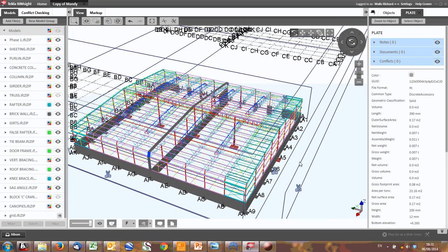When the wind blows on this side of the building, how do those loads get supported? If you don't know where the loads are going, you have a very big problem. That may mean your structure is not stable. You need to be able to say, if any load is applied anywhere to the structure, you know how it gets into the floor. And also when load is applied to huge areas, you've got a wind load applied to this entire roof and all these sides. How does that get into the ground? And how do those loads come together to produce a structure?